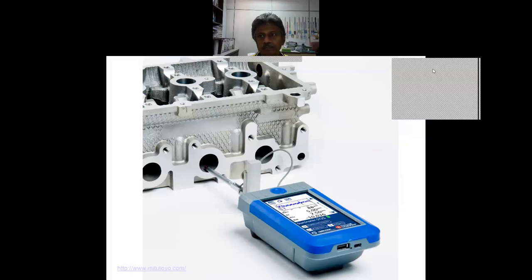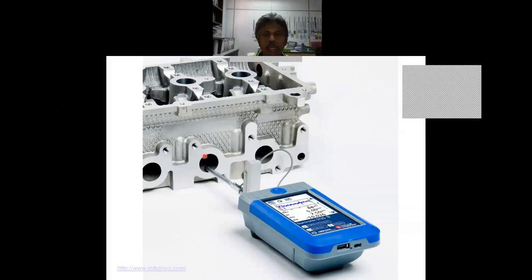Okay, so if you look at a cast like this, probably inside this hole, roughness is very important. And this picture actually shows one type of roughness tester known as a portable roughness tester. So this kind of roughness tester, you can bring it to the product. This product is so huge, you can't really bring it to the lab or put it on a surface for measurement. So we bring the instrument to the product. And so we put the instrument here.